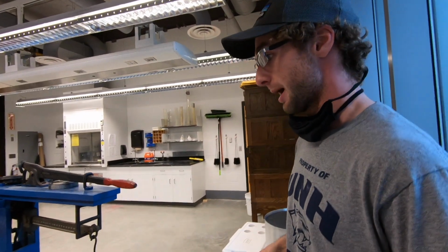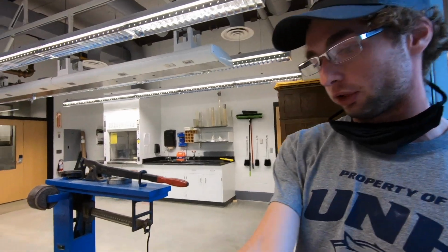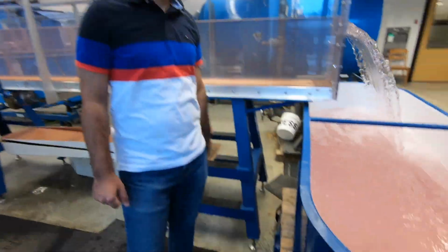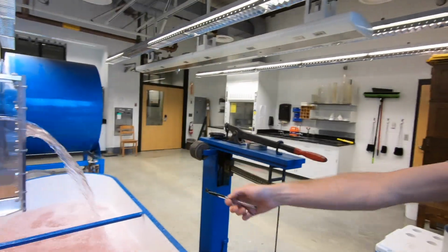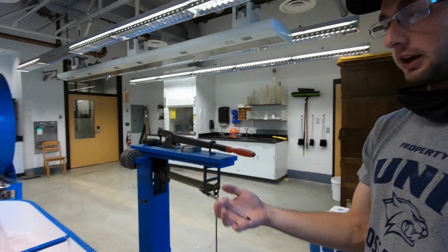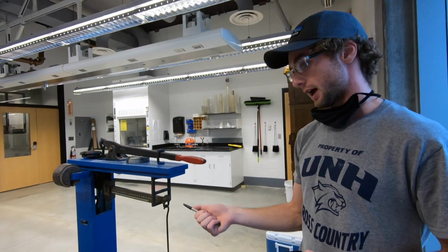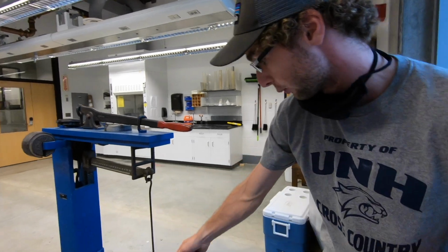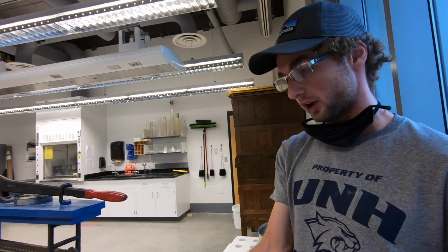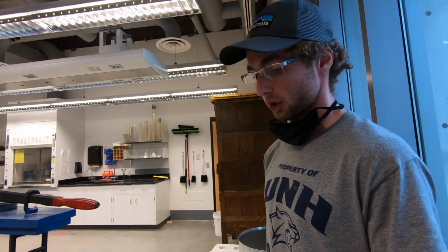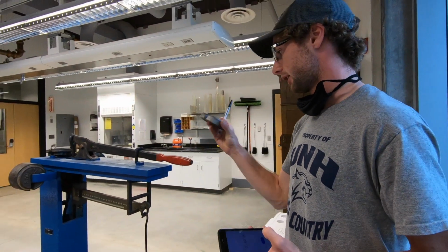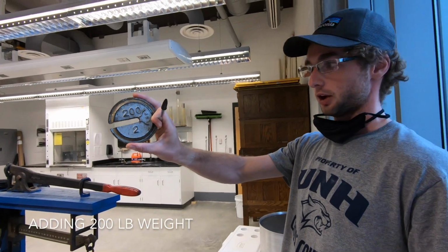So we're going to do the weight tank for trial 2 now. What's going to happen is that Roosevelt is going to pull the lever over there, causing the flow to be cut off from the bottom of the tank, causing all the water flowing from the flume to stay in the tank and increase the weight. At this point, the weight over here equates to being more than what's in the tank. A short time after Roosevelt pulls the lever, the weight of the water in the tank is going to be greater than the weight on the scale, at which point I will start the stopwatch and add the equivalent of 200 pounds to the scale.